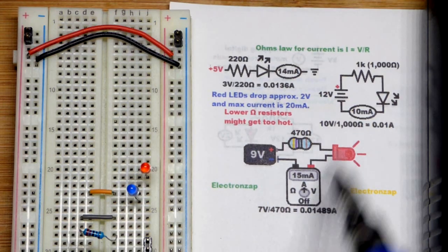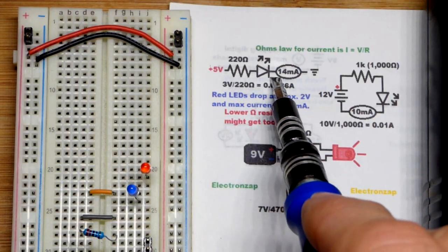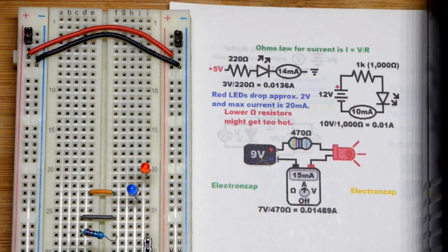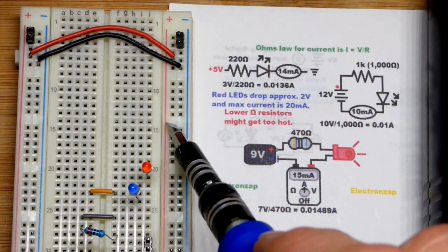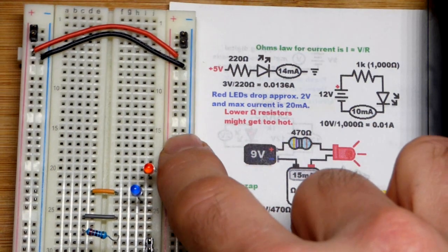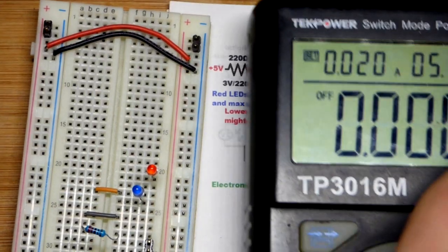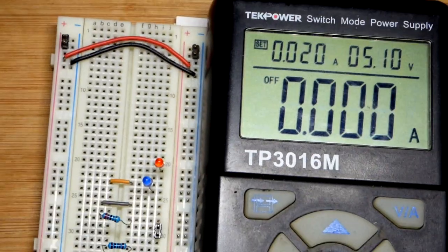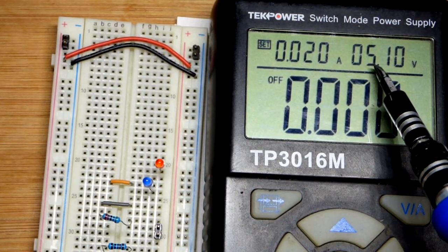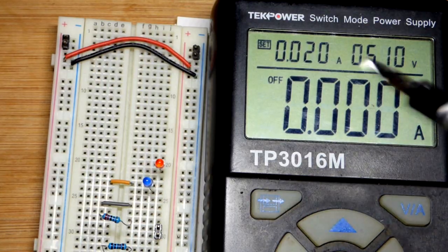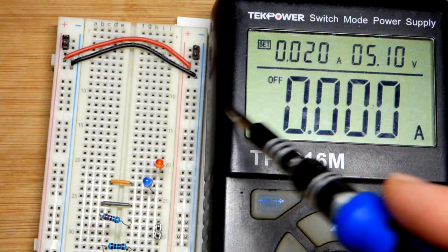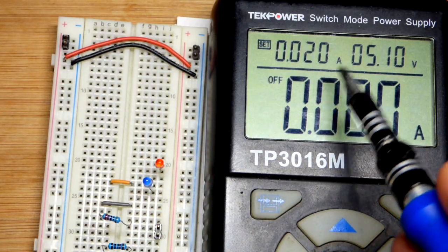So now, once you understand the basics of a circuit from the schematics, maybe a pictorial, and then reading about it, or in this case, me explaining them, you want to actually build those circuits. So generally, you'll do that on a breadboard that we have right there. This is a cheap one, but cheap ones are plenty fine. And then a power supply. So this will simulate, in this case, a USB output. They're about 5.1 volts. If you're going to power something with that, you can plug into a USB. There's alligator clips that come out, and you could power the breadboard if you have USB power sources laying around.